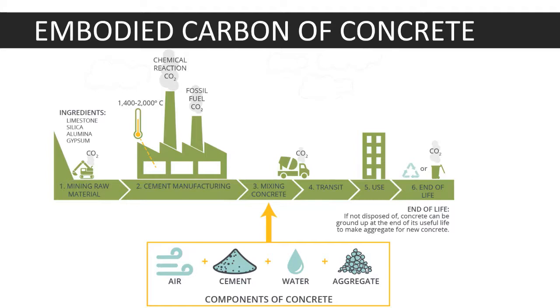Concrete is a material that produces a lot of CO2 through its manufacture, in particular because of cement. Cement manufacture contributes to greenhouse gas, both directly through the production of carbon dioxide, when the calcium carbonate is thermally decomposed, producing lime and carbon dioxide, but also through the use of energy and the combustion of fossil fuels.